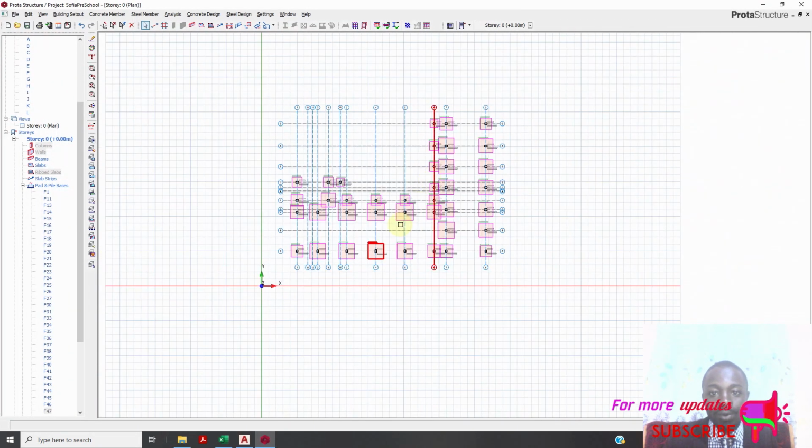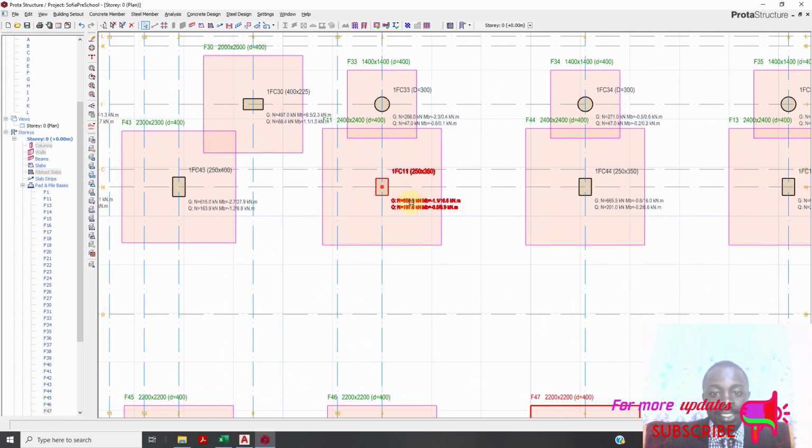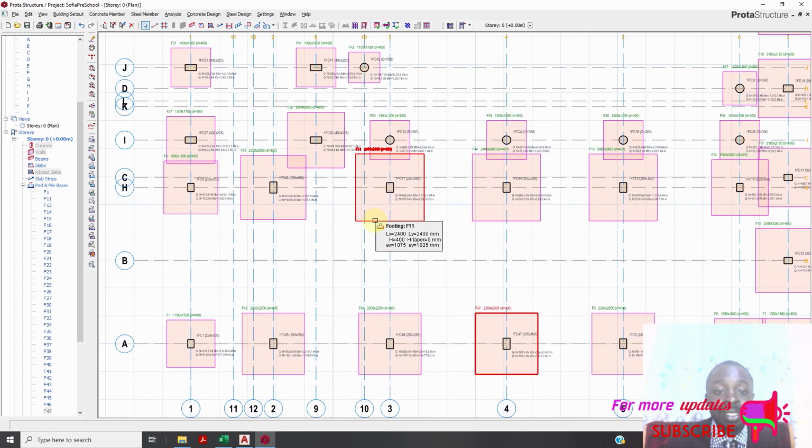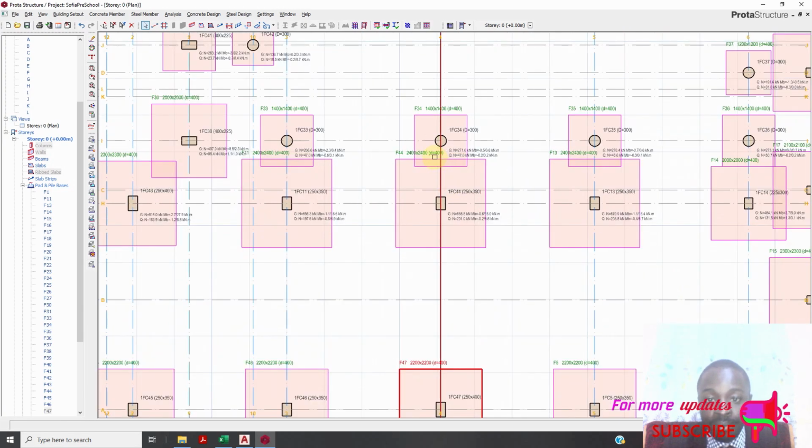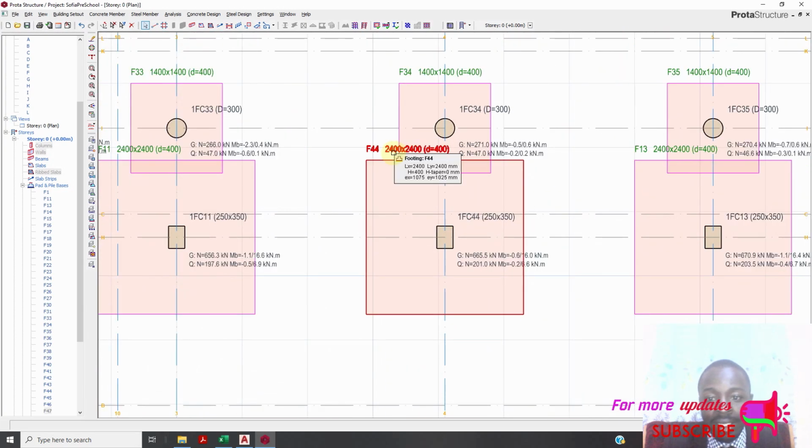That's how sometimes the design is done, and to your surprise, you realize designing halfway will make you faster and more accurate. So you can just design halfway instead of doing the design of the entire building, which has symmetrical parts.